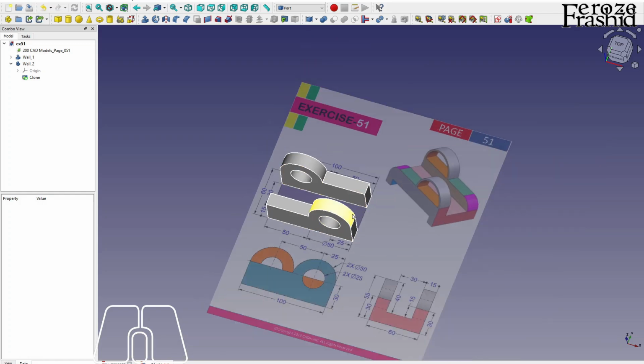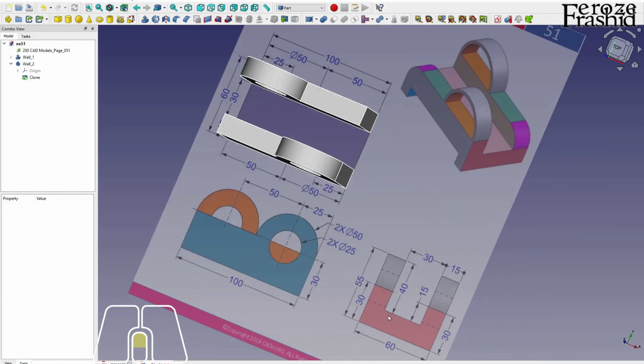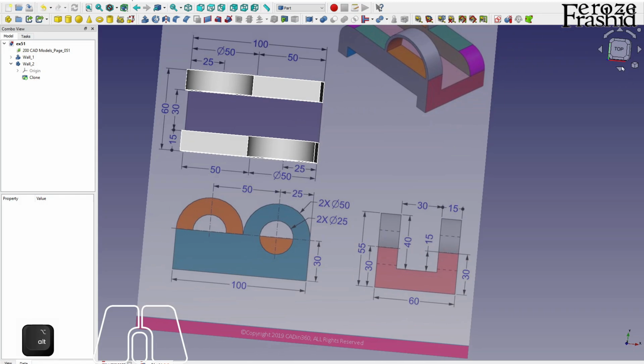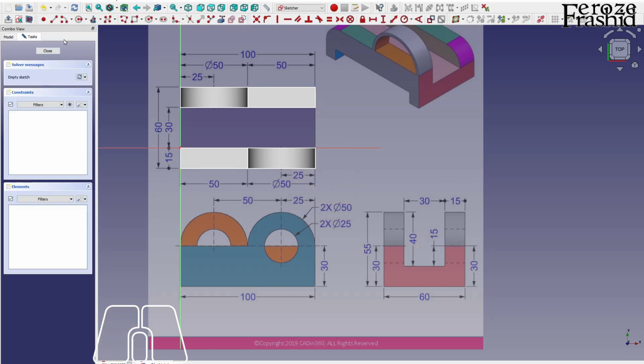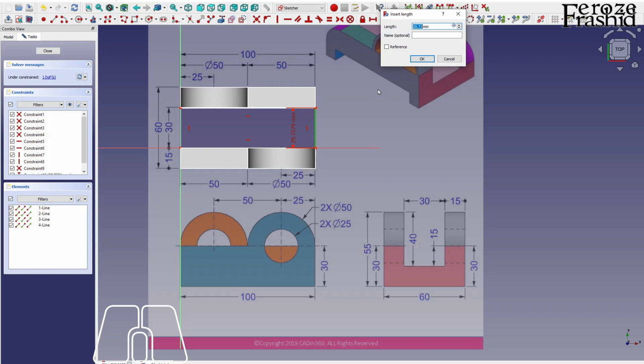The only thing left to do is the base, which, we can see from this side view, is a plain pad. I don't see any indentation in here, so what I will do is build a pad on XY plane, and I will just build a rectangle. I could go with a cube since I'm in the Part Design. So this is going to be 30, and that length,